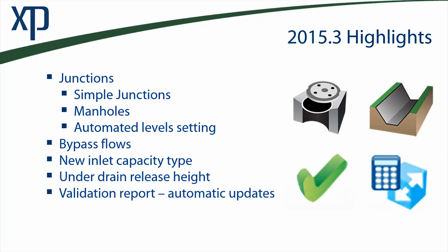With more capabilities added to the design elements, we've boosted the validation report so that you can flag potential issues with levels, and we've also built in some automatic solutions, saving you time in iterating the design later on. Finally, we'll be reviewing our new comprehensive water quality volume report to show how you can demonstrate compliance with local runoff reduction requirements.